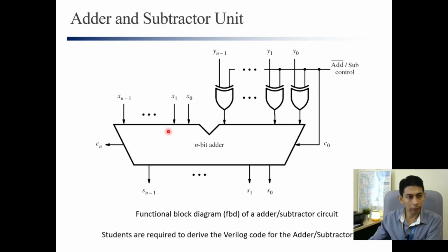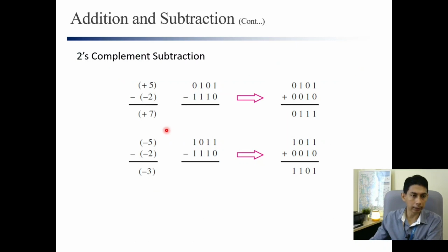When we look at our digital system, we need to know the size of our system or our data, our number. Because we want to process or store the data in hardware, and the hardware is actually limited. For example, if the size of our adder is 4 bit, the number that we can process or manipulate is 4 bit only.